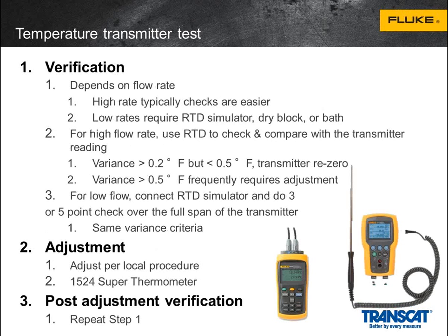Temperature actually is kind of interesting in that, despite the fact that it's the least important of the measurements in the gas custody transfer measurement, calibration measurement, it actually tends to be the most complex. It depends very much on your flow rate. If your process is shut down, you pretty much are going to have to use an RTD simulator, and it's best if you can do it in conjunction with a dry block or a bath like we talked about earlier. So if you have good flow through the system, you're going to simply use your RTD.